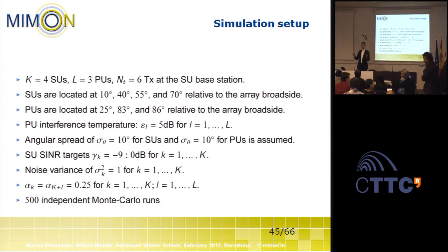It depends also on the separation of the antennas. In a micro cell we had large separation, so we could achieve very narrow beam width. But in a Femto cell we don't have the freedom to have such large separation. Oh, but you can still have half wavelengths. I think that's not a problem.